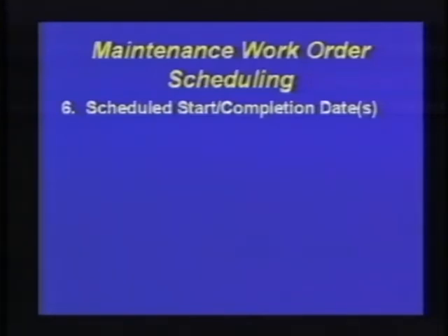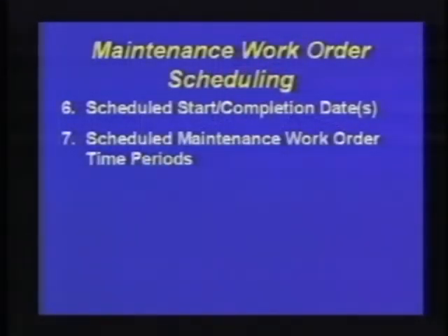And now we've integrated the planning of labor and spare parts, and now if those spare parts arrive according to the required date on the purchase order, assuming the item is purchased, and since 99+% are purchased, then we're ready to schedule, which means I could put a specific date and shift on that order and release it to a craft person, and that order goes from planning to scheduling to release in that sequence.